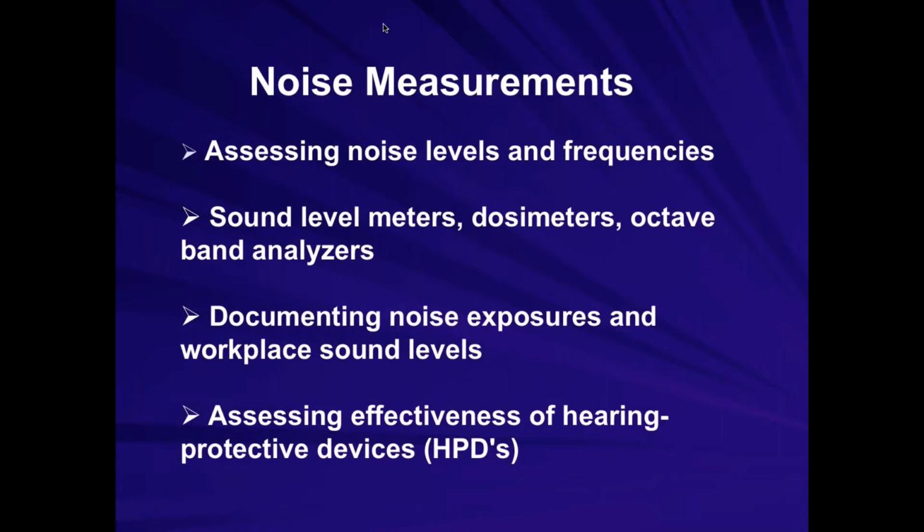So instead, we use a system of measurement called decibels. With decibels, we're taking those sound pressure levels and converting them using a logarithmic scale. What happens when you take a logarithmic scale? You compress a very large range of numbers into a much smaller range. So typically, we're working with anywhere from 0 to 140 decibels instead of that enormous range of 20 million. That really represents the real pressures that we're dealing with. It's really not just a log, it's kind of a ratio, and I'll show that to you. You don't have to read for our class.